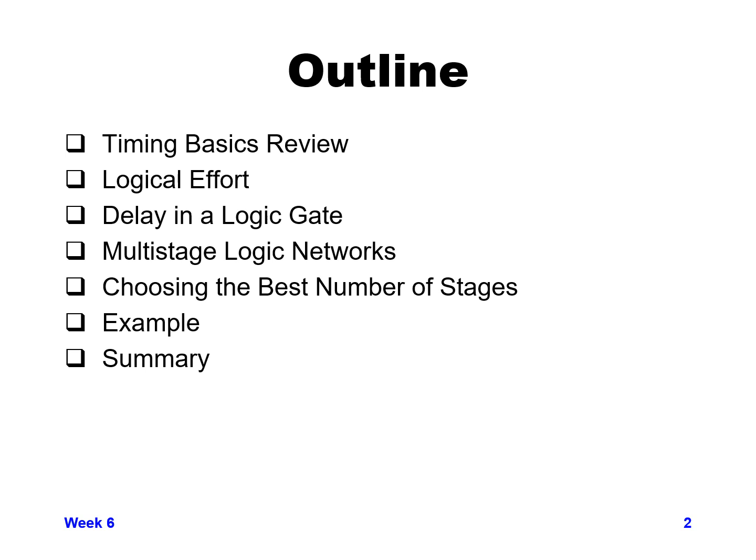Then going into more detail on timing, introducing the concept of logical effort, and then the delay in a logic gate, going through multi-stage logic networks, and how to choose the best number of stages and sizing of stages in order to get the best delay, and then going through an example, and finally a summary at the end.